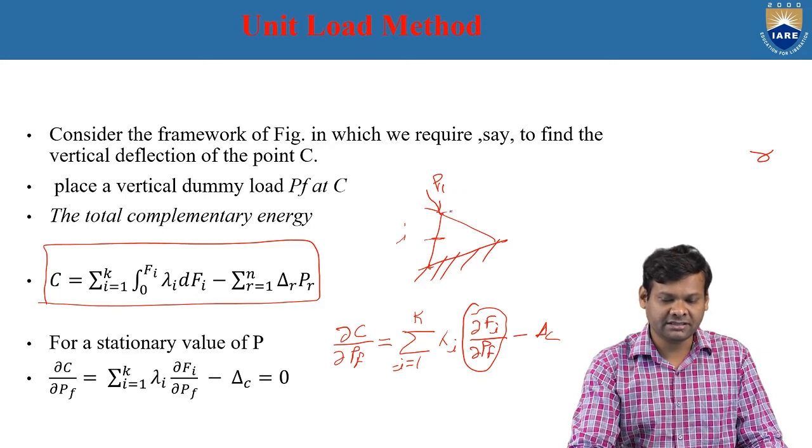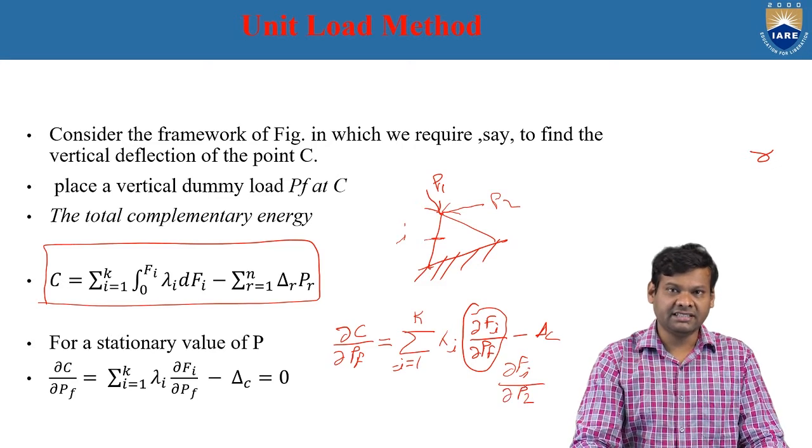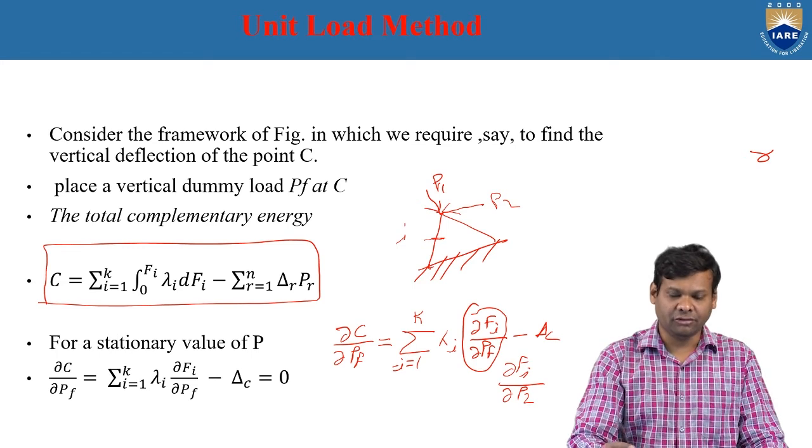If we apply some other load P2, then it is called dou F_i by dou P2. That is the change in force in an element due to a specific load.